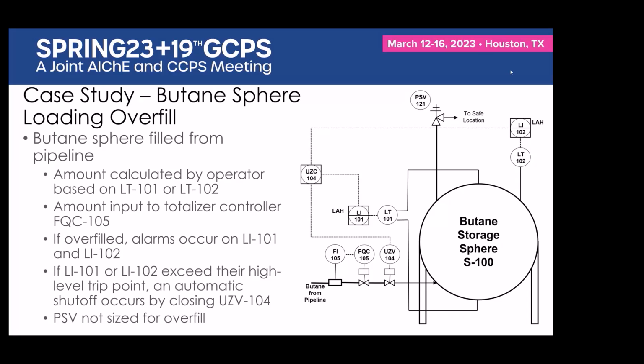allow you to define beta factors and assign them to events. We don't do that. We want you to explicitly define what the common cause is and show it in the fault tree. We deliberately chose that approach because in some of the other fault tree tools, when you just define a beta factor and assign it to pieces of equipment, sometimes it will calculate things in ways that you would not know, understand, or expect.